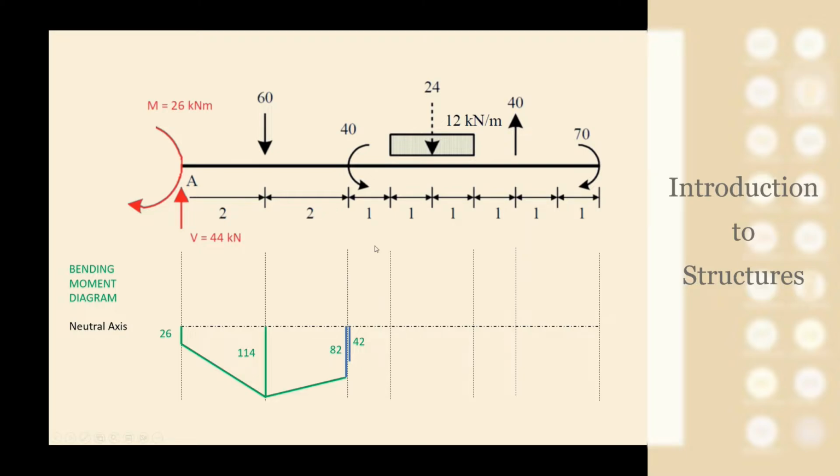And now I can add this line of a linear variation of the moment and see what happens when you have a moment applied on a beam in terms of the diagram. Before the moment you have a value, and after the moment you have another. This is because this moment is applied exactly at a particular cross section and produces this sudden change in the diagram.